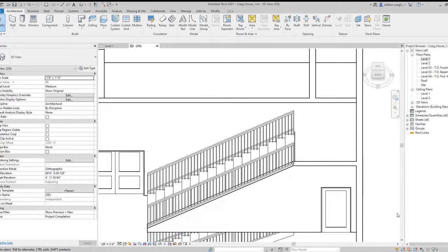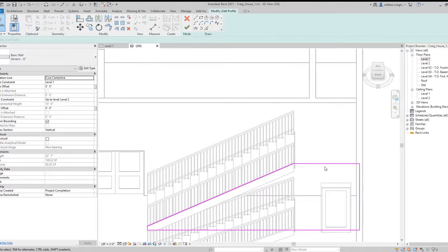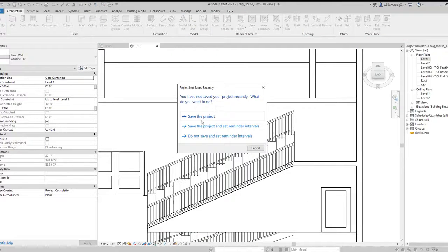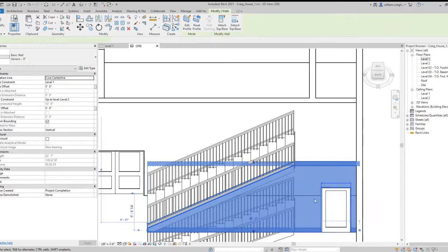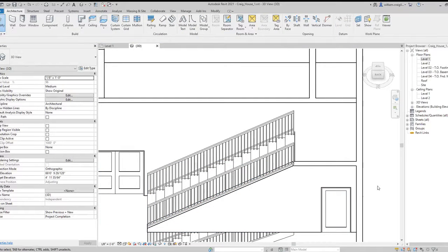that is cut down. So you're able to do this, and you can make multiple shapes if you wanted to in here just by going through and editing the profile. If I wanted to, I can make a curve in here if I wanted something weird in this wall. But once again, save project, yes. Save often, save well. That is an easy way to do a wall and then cut it down.